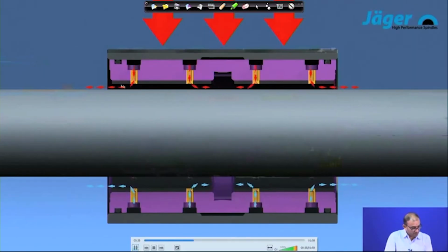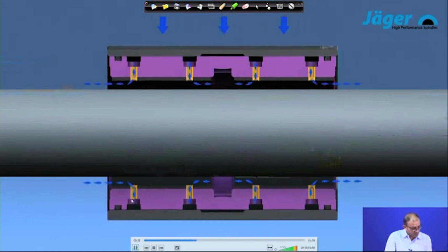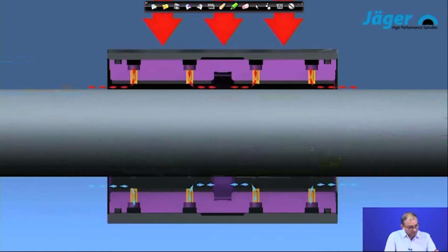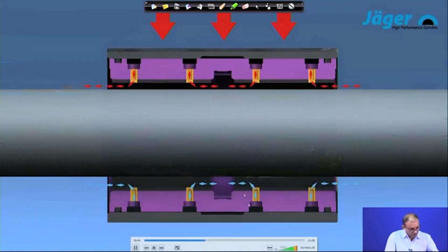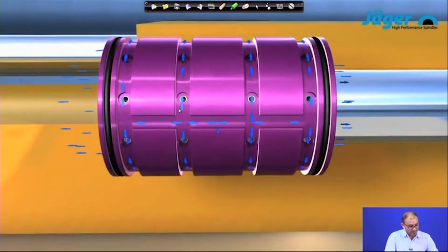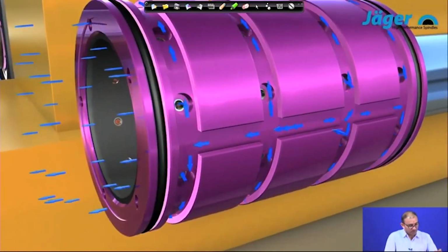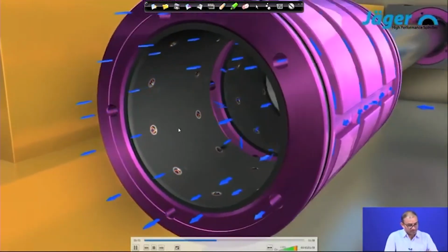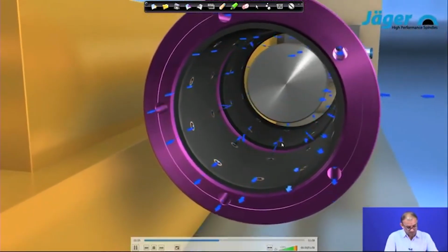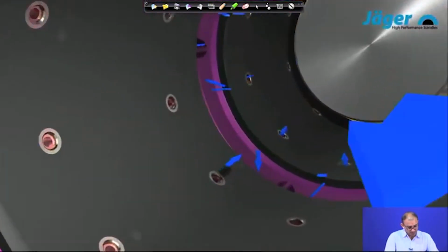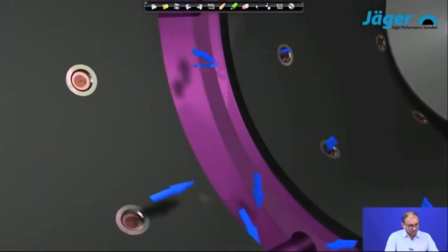Right. So, in this location this is a red color, that means high pressure, again both things are maintained, now both things are in blue color. Again it will go down, this becomes less high pressure, this is a low pressure zone, again it will match the part. So, in this way what is happening, this is a self-adjusting bearing. So, wherever there is a pressure difference it will maintain that pressure difference by the pressure regulator of this particular air bearing. So, this is how it is useful.